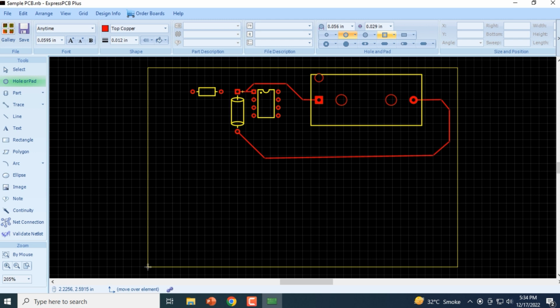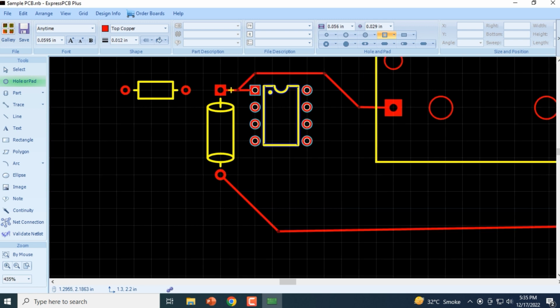And now that's a square box. So that's a hole with square pad. Now this is used for, again, inserting wires and components and for connecting to other board layers. Square shape usually indicates pin 1. So if you want to connect something like this out here, I'm maximizing this. Now this is pin number 1. If you want to insert a pad here, you'll have to click on this. So now you've inserted a pad here.